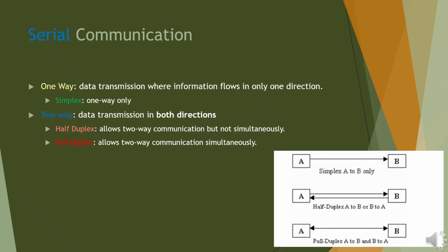Half-duplex and simplex systems typically use a single data line, while full-duplex systems require separate lines for transmission and reception. If high speed and reliability are critical, full duplex is usually the preferred choice. However, since the number of wires directly affects hardware complexity and cost, simplex or half-duplex configurations may still be suitable for simpler or low-cost applications.